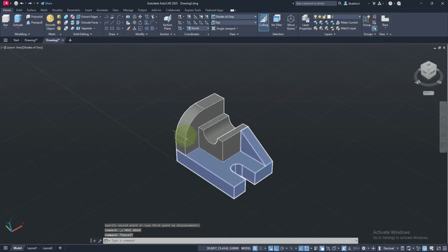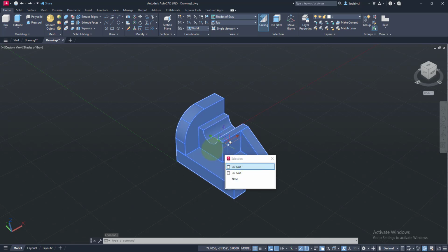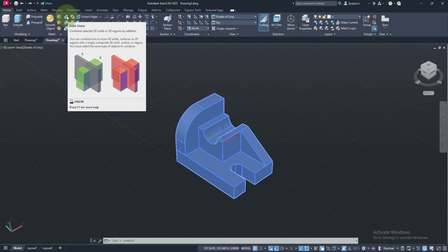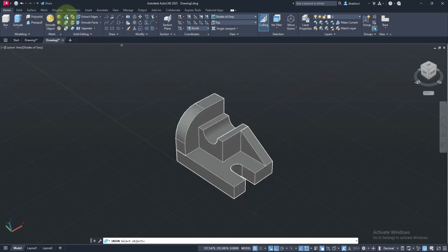I'll select them separately, select the base as usual. When I move my mouse to the next body, you can see a cross icon around my crosshair. I'll select that shape and I'll click on the next object. There I have 3 of them, 3D objects. Now that I have 3 of them selected, the next thing I want to do is to use a command known as union. Union helps you to merge solid objects together to be seen as a whole. So I'll go ahead and click on the union.